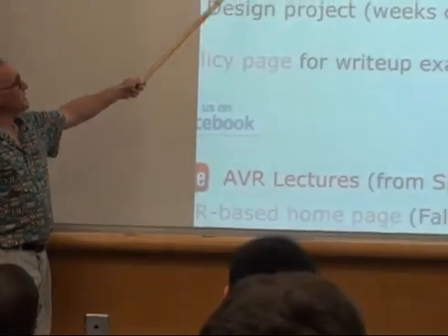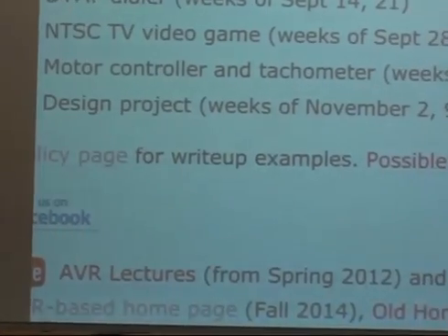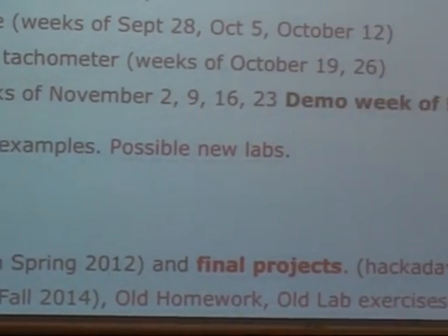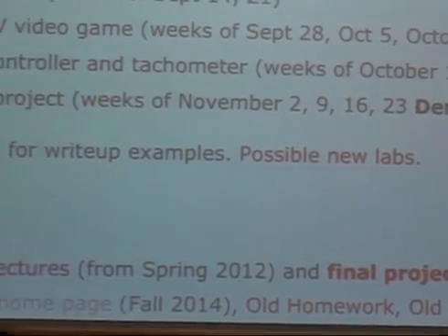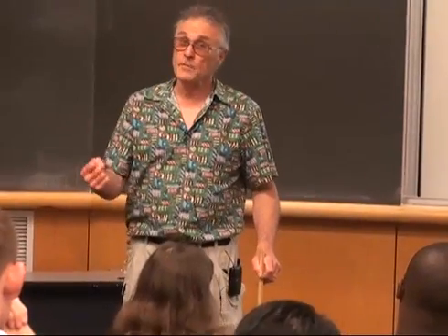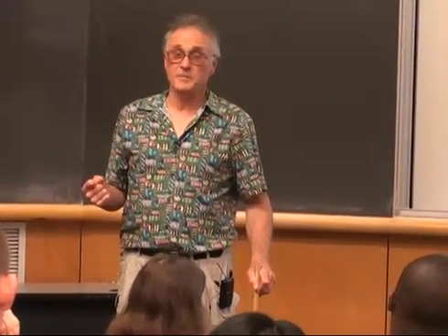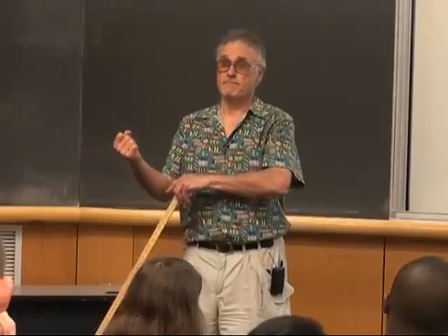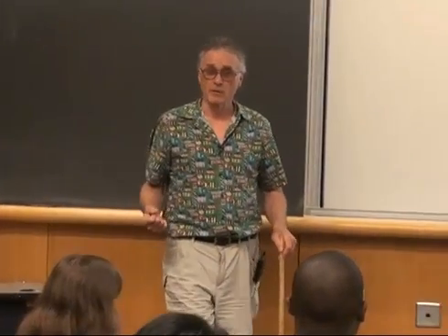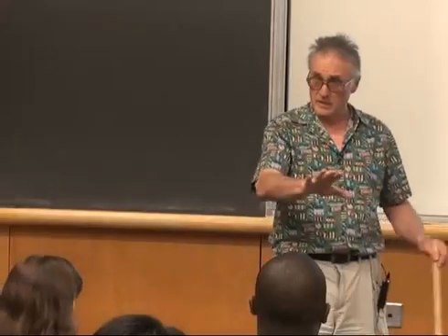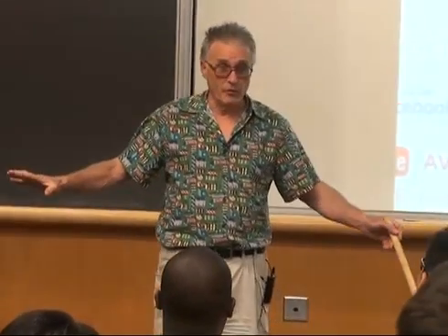Then we're going to do an NTSC television video game. NTSC is an old analog standard. The reason for using it is that the write rate to the television is very high, so you can do good animation. Also, a television screen is the cheapest LCD display you can buy. They make millions of them, even though this isn't used for broadcast anymore, right? This is completely obsolete for broadcast.